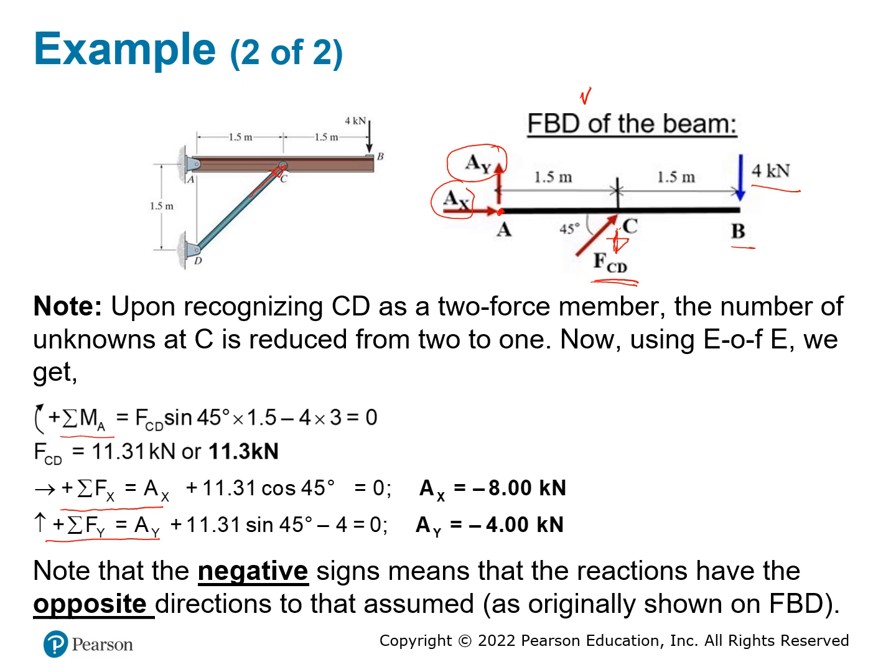And A is the best point to start with. When you do that, you look at the force at B, that is equal to this much of the moment. This is clockwise, so we put a negative at the front. And this one, FCD, how do you do that? Well, this is what we did in chapter 3, or maybe even in chapter 2. You need to find the perpendicular distance from this force to the point A.